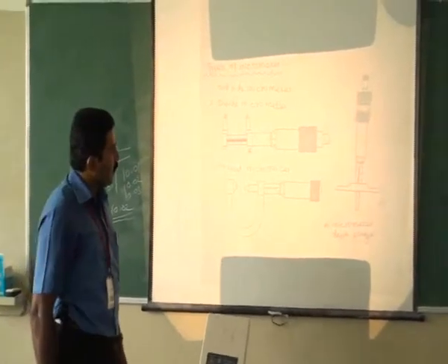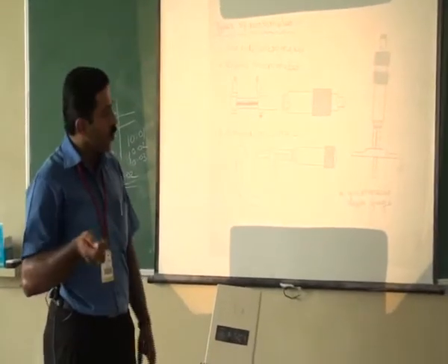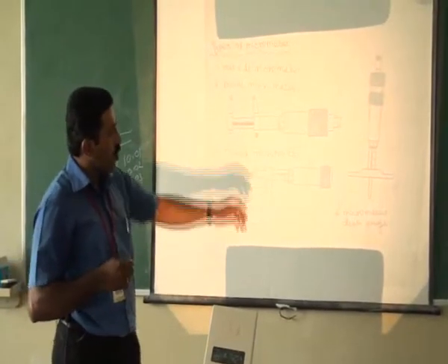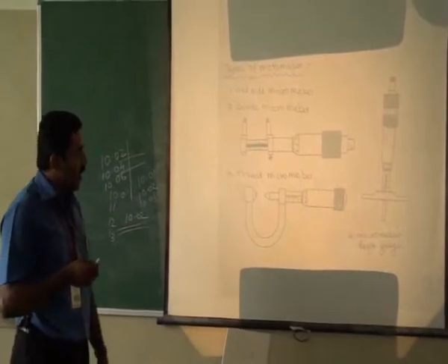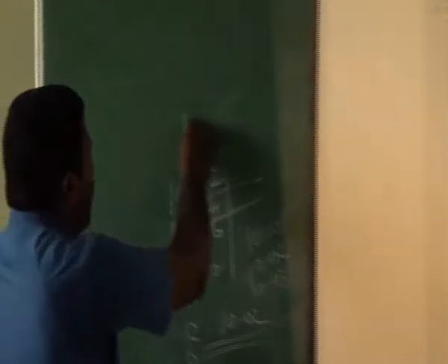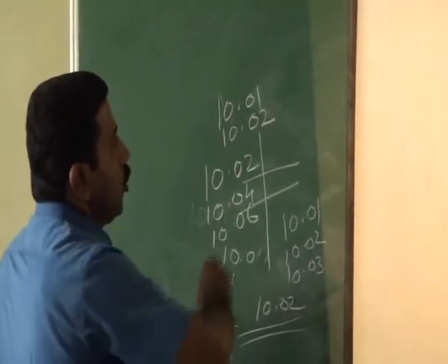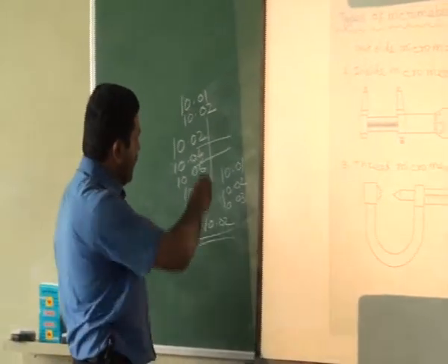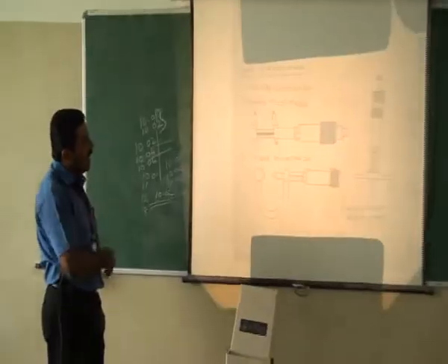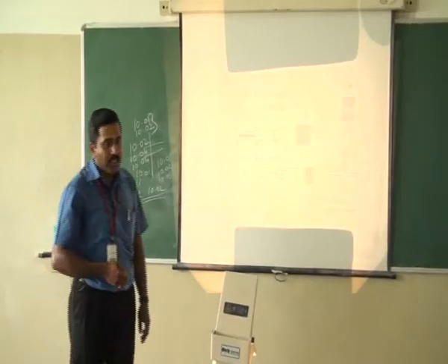So the various types of micrometers we are using are digital type micrometers and bench type micrometers. Why are we using the digital type of micrometer? Because of accuracy. Based on the observer, the value will differ. Observer to observer, the value will differ. Some persons calculated 10.01, and some persons calculated 10.02. The digital micrometer displays the value and does not give this variation, so it will give the accurate value. So that is the main thing.